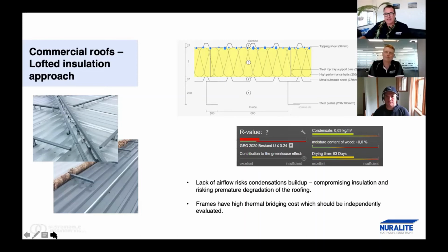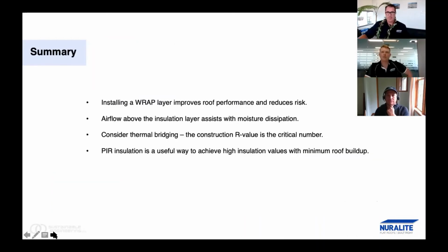Yeah, no, absolutely. Obviously, we never actually came to a result on that calculation. Ended up with a question mark there, and it's dependent on so many things. It's dependent on that metal tray underskin being completely airtight to stop that moisture air rising. I haven't seen two sheets of metal flipped over one another to create an airtight seal ever. So something to consider there. So good points all around.